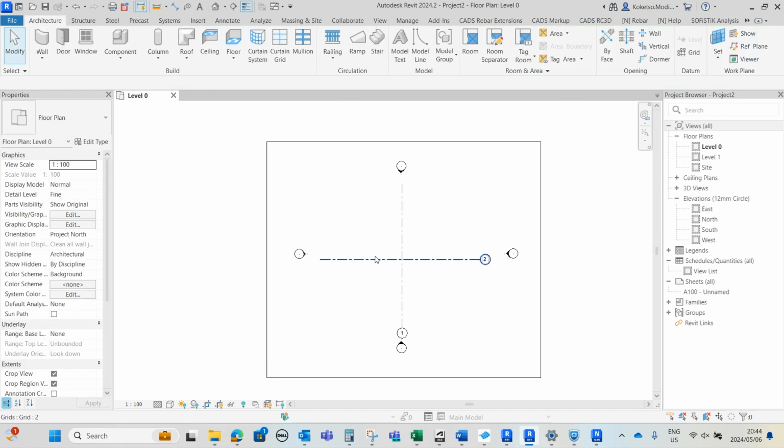So since we open up our project, we're gonna use family templates and then we're gonna generate our families and then assemble the bearings inside our project. We're not gonna model it as a single family because I want the quantities and also the elements to be as separated as much. I want to separate the elements as much as I can. It makes it easier for manufacturing guys to quantify and also to demonstrate how everything is assembled.